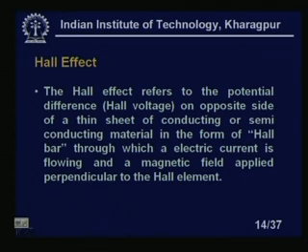I will repeat it. Okay. I have a bar, looks like this one. If I take this one as many times amplified or something like that, that means I will apply a magnetic field which is coming through this and going out of this, right. I am applying an electric current which is entering through this and going out of this. That means I have applied some voltage, that is the reason some current is flowing. If I apply a magnetic field here, you will find that across these two surfaces, this and this, a potential will be developed. That potential is what we are calling the Hall voltage.